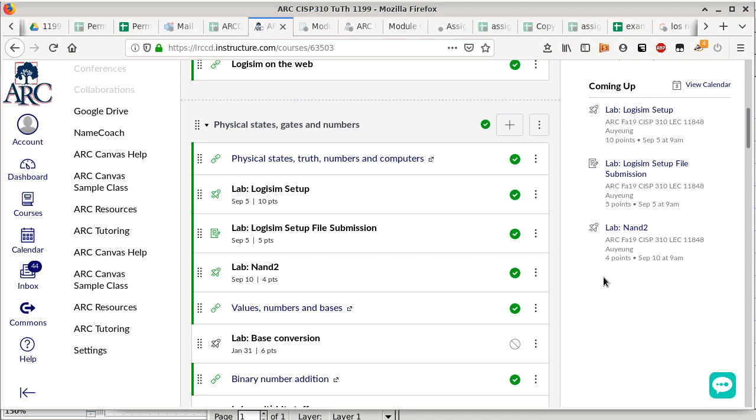Well, I hope you had the chance to review the material before the class, because so far we have made the connections from physical quantities and physical devices like electrical charges, relays, and transistors. We made that connection from physical stuff to logical stuff because we just made a NAND gate in the previous class using two N transistors and two P transistors. So are we okay with that concept? Okay.